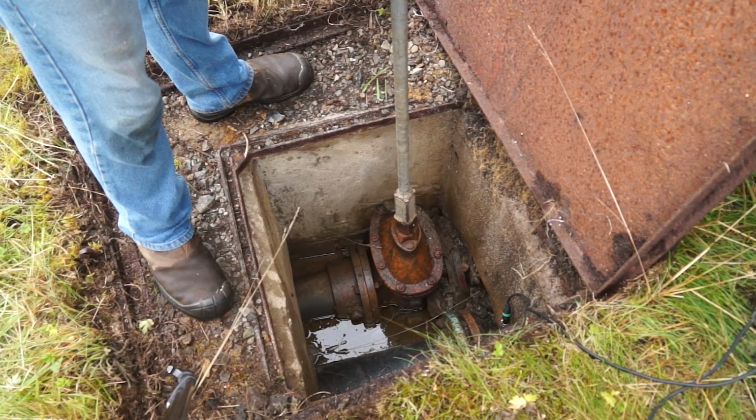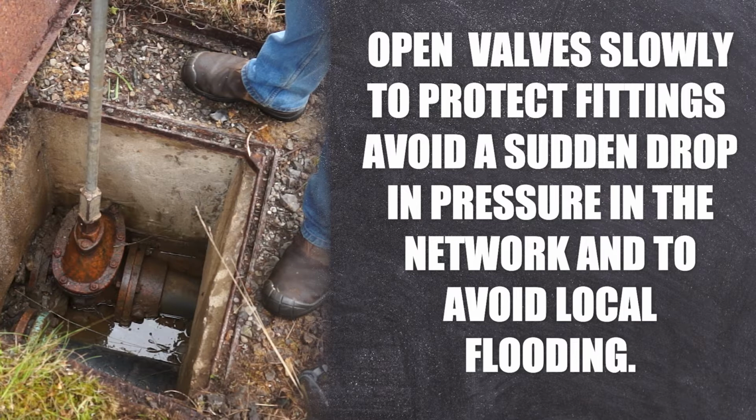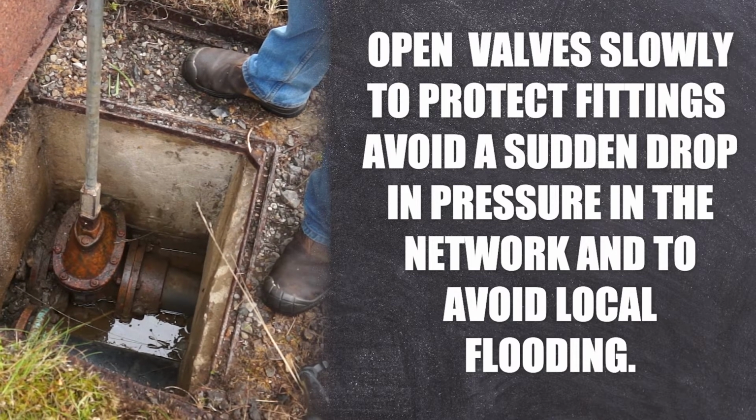Why are you doing it slowly? To stop any damage to the line further down on fittings or pipework. There's a tremendous volume of water behind me, and to let a surge of water down the line could cause a lot of problems.